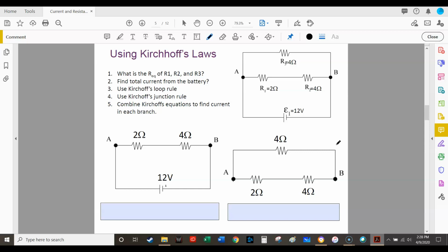All right. Well, here we go. What do we have? So we have 12 volts right here. Okay. So this is a 12-volt battery. And since this branch is in parallel with the 12 volts, we know it's getting 12 volts. And then this top one, R3, is also getting 12 volts. So what we could do is just say this. It's getting 12 volts, right? Because that's the third rule. 12 volts divided by 4 ohms, that is going to be 3 amps. Okay?